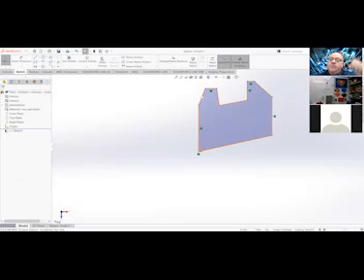We know we've got the lines there, none of the sizes, none of the constraints. And I'm going to wait right here a minute and let everybody get to that point. Don't worry about it being exact. What you do need to have is the 3 lines that form the bottom. You need to have the 3 lines that form each of these ear pieces, these little widgets that come out, and 1 horizontal. So we got 6, 9, you should have 10 lines drawn. Okay, and do make sure the last line does go back to your first.